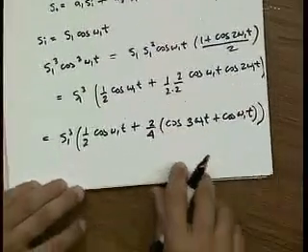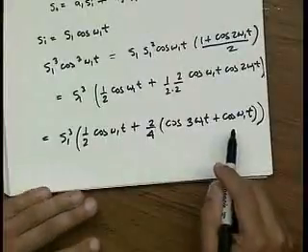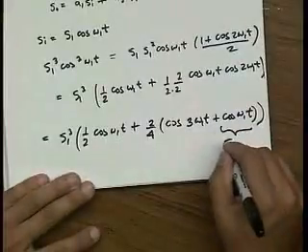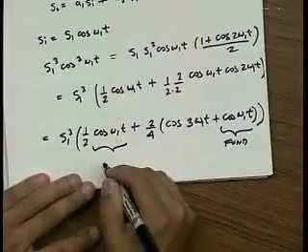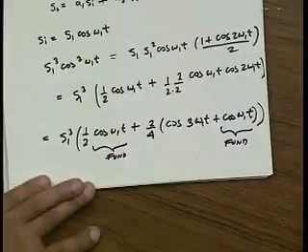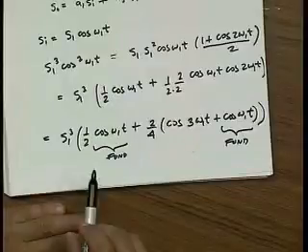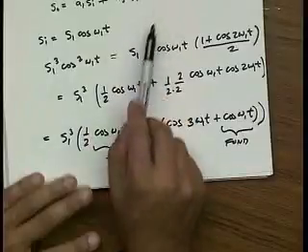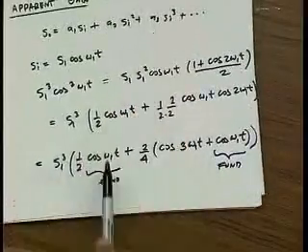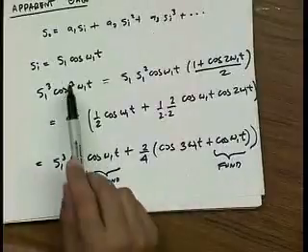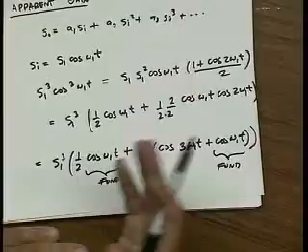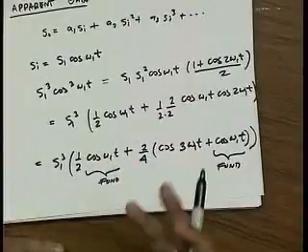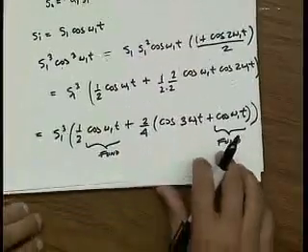Okay? And it's really this difference frequency that's very important, because this is at the fundamental. And so we see that the cubic operation generates two fundamental signals, and depending on the sign of A3 in this expansion, these fundamental tones could either add to the linear gain term or they could subtract. And so for a compressive nonlinearity, they do subtract. So let's collect these terms.